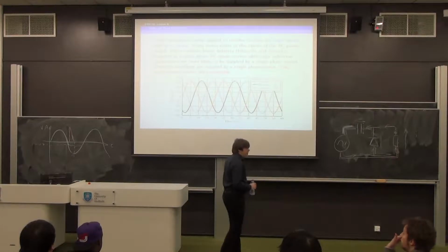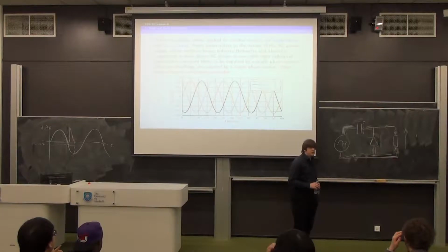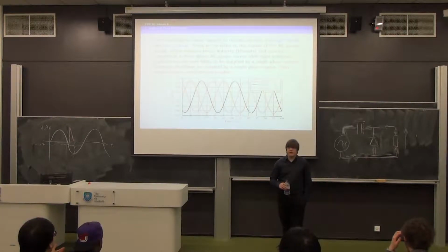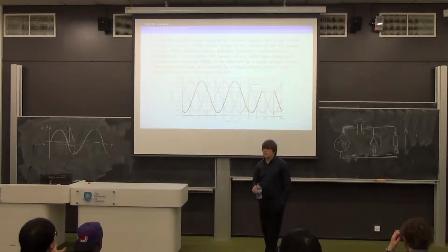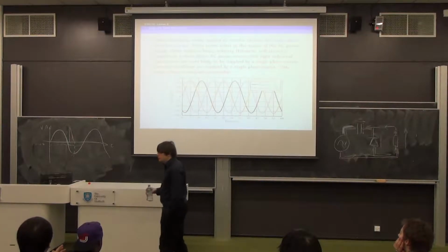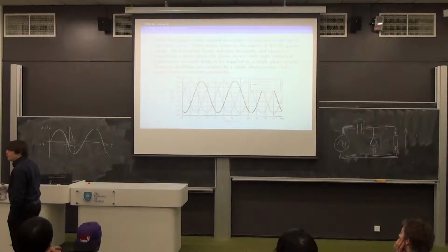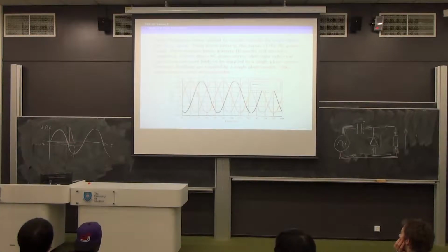In situations where we want to supply a lot of power, usually we'll take three lines in which are carrying a voltage which varies with respect to the neutral, and the time relationship between those voltages is shown in the graph on the slide. The advantage of this is we can provide more power, and that we can recharge any energy storage components, capacitors or inductors, 3 times more frequently. The result of this is,